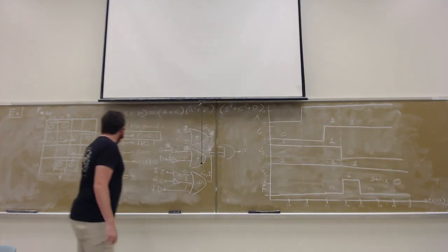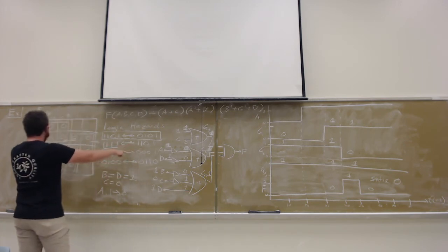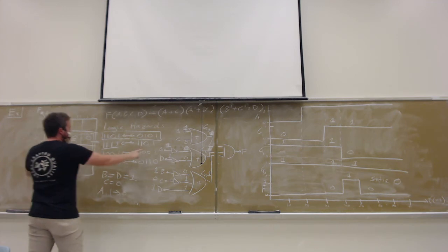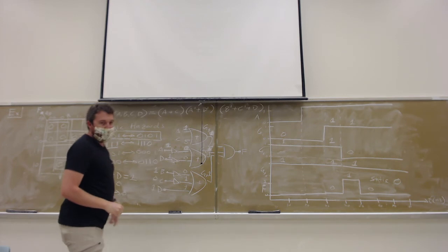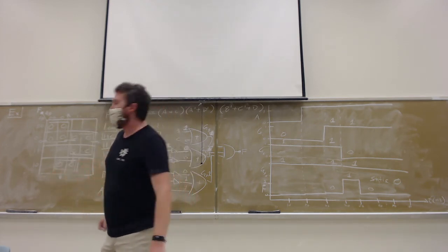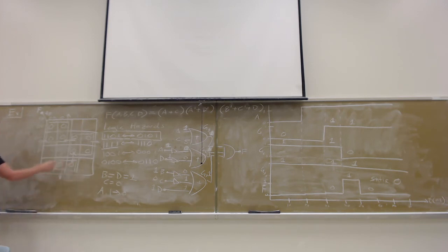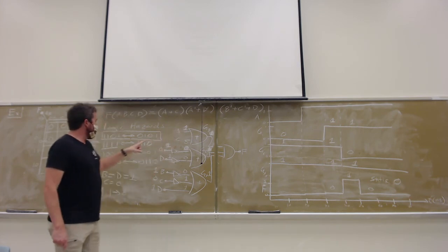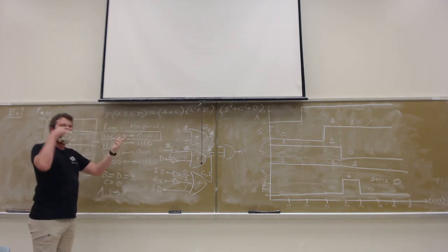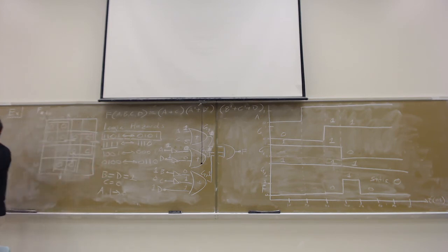Someone on Discord says there was a typo, that this one, let's see, 1111 and 1110. Oh, you're totally right. Good catch. Who was that? Aaron, good. This cell is 1110, not 1101. All right. So this shows that the same junction, the same presence of the hazard, depends on which direction you're going for the hazard to occur. It won't always be on both of them, but it will be on one of them.